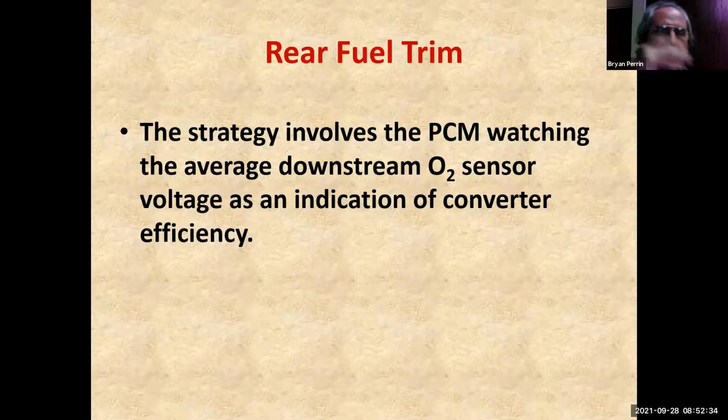So back in 1983, Bosch said, look, we can control the fuel mixture, control lambda from after the catalytic converter. What we cannot do is control the catalytic converter. So the front sensor's job, which is controlled by short-term fuel trim, is to make the catalytic converter function. Rich, lean, rich, lean, rich, lean. The rear sensor's job on a modern vehicle is to control the emissions coming out the tailpipe. What's our mixture out the tailpipe? Where are we at?